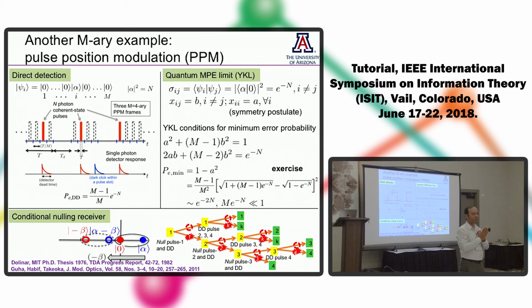So it's roughly like a lower signal. Sorry? Roughly speaking, can we think of the photon number as SNR? Roughly speaking, photon number can be thought of as SNR, because remember that when you get a laser light pulse, you have no noise in it. All of the noise is added as a result of the detection. But think of homodyne detection. Homodyne detection gives us a signal to noise ratio of n over 1/4, where 1/4 is the noise variance. So if your n is smaller, your SNR is going to go down.